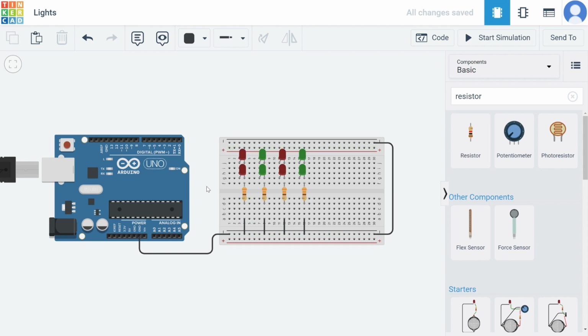And we need to have a really good numbering system. So when we're writing the code, we want to be able to think about what number pin would make the most sense. Now, I usually don't use 0 or 1 because they connect to something else which can interfere. So we could use 2, 3, 4, 5. And so what we might do is take this, and I'll change the color of this in a minute. Try and keep it as neat as possible by clicking to make corners.